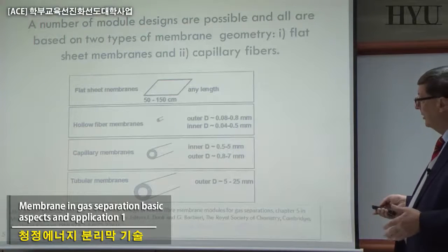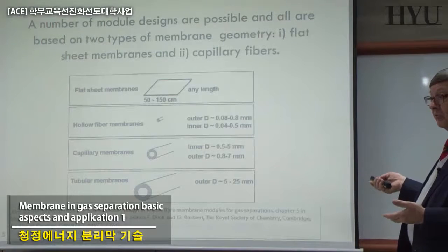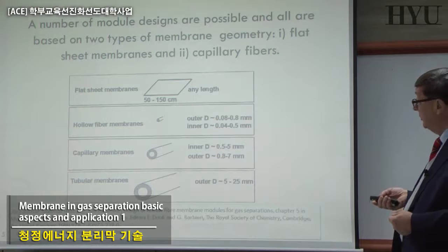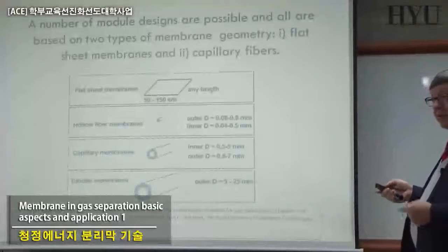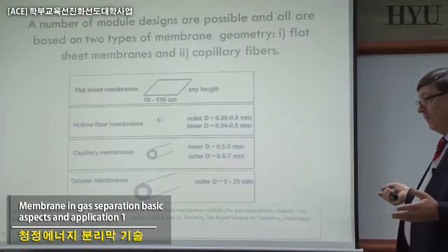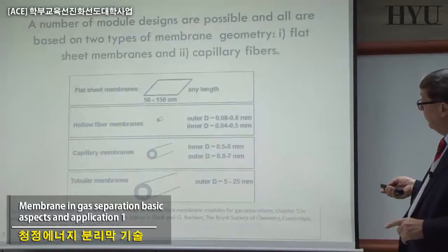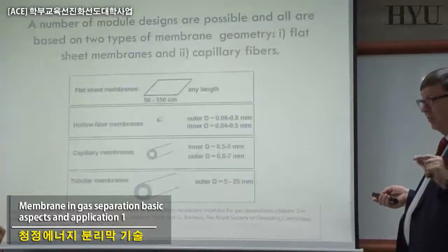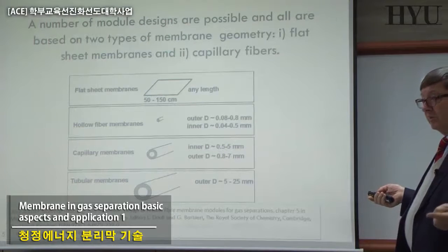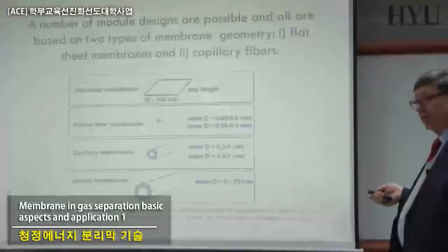They are doing it because when you operate, you can have different performance depending on the geometry of your system, particularly in terms of energy consumption, fouling problems, the interface, etc. So going from flat sheet, for example, to hollow fibers, there's a big difference, but you have to understand why. Just to anticipate, contrary to what we have been discussing in the liquid phase, most of the membranes that people are using today at industrial level are hollow fibers in gas separation.